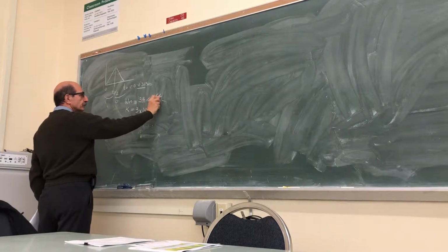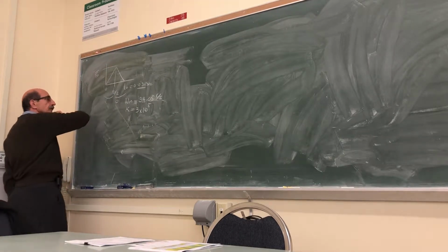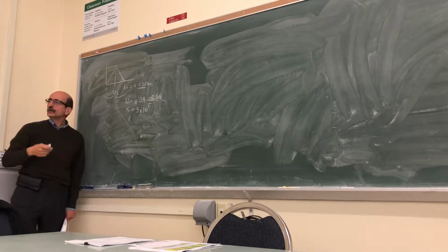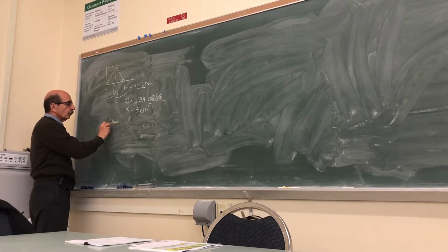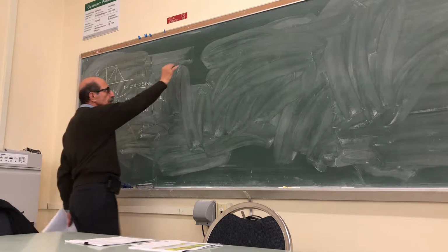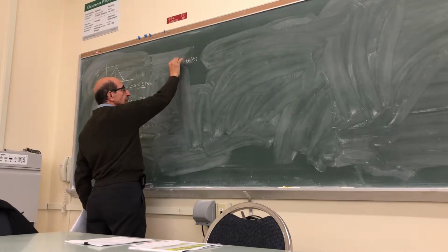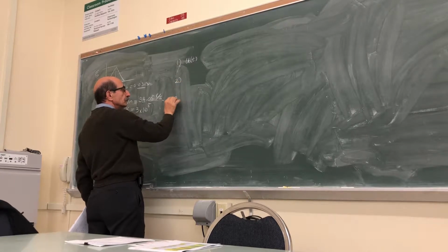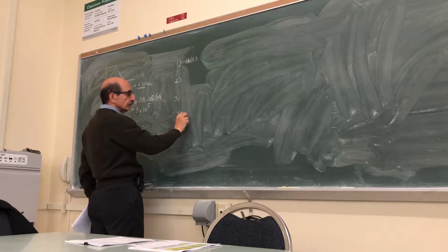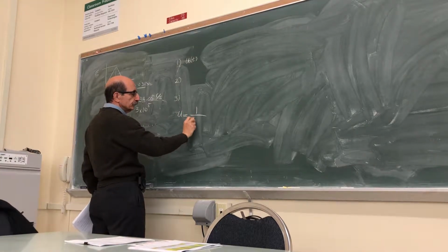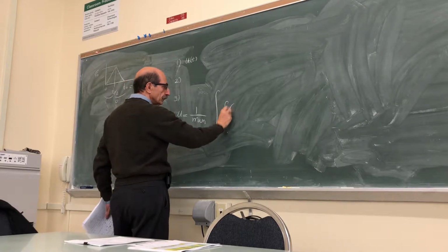Radians per second. So this was the loading, and then we wanted to find the maximum displacement, right? So we derive u of t for each case, right? Case 1, case 2, case 3, using this Duhamel integral.